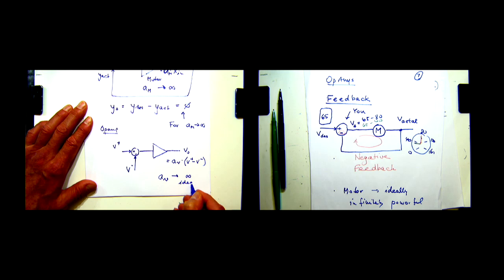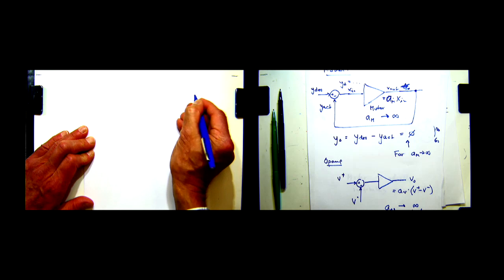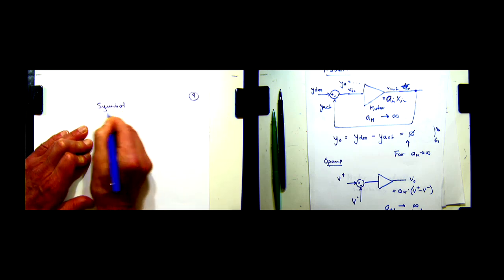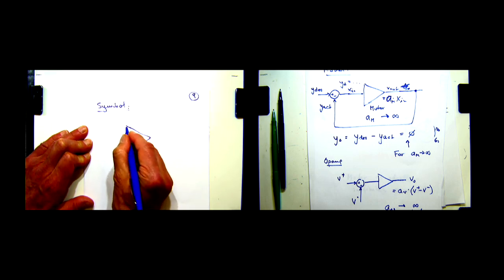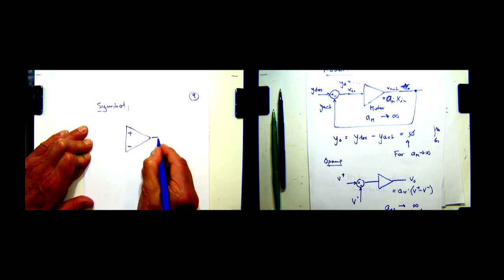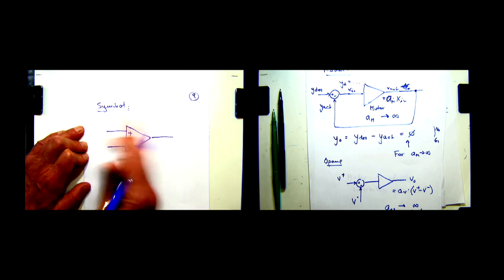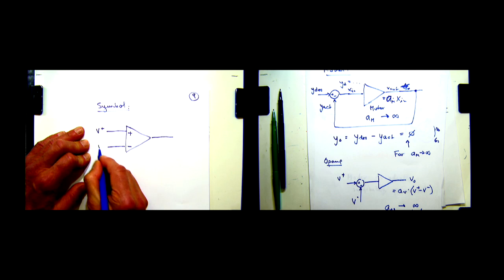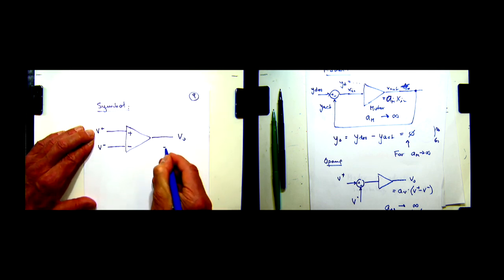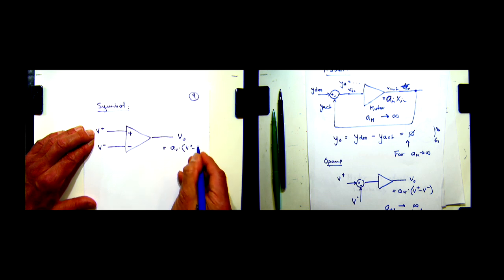And AV of the operational amplifier is going to be infinite, ideal. And in practice, the one in the lab may have a gain of maybe only 100,000 or a million or so. Let's not worry about that little difference, okay? You have to build extremely high gain circuits before that matters, and you will have other problems. Okay, so the operational amplifier also has a symbol. And this is the symbol for the operational amplifier. We simply put that funny little round box to calculate the difference, sort of sweep that into the triangle. So here we have voltage V plus, here voltage V minus, and here voltage V out. And again, V out is going to be equal to AV times V plus minus V minus.